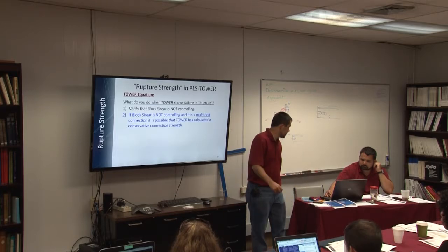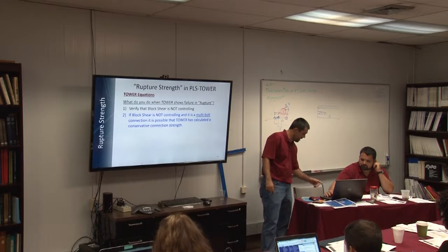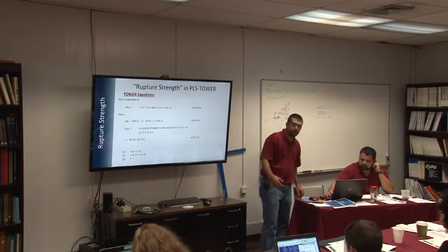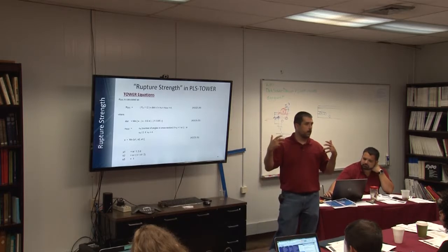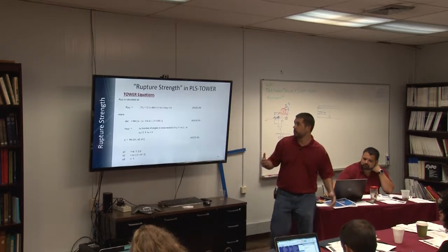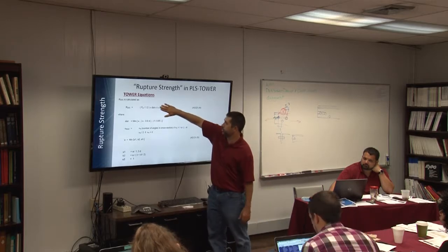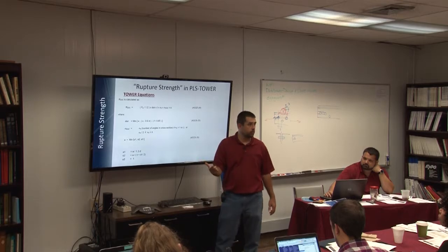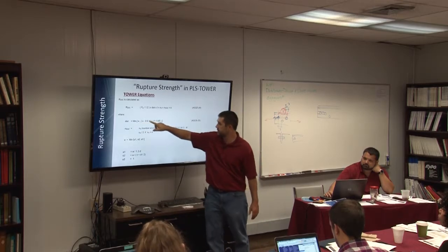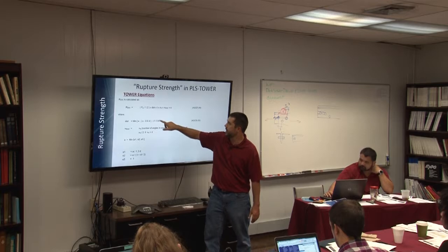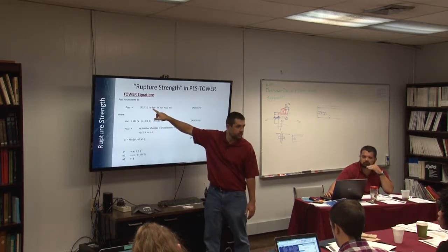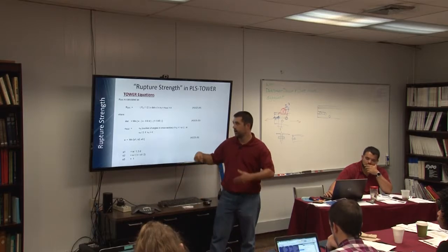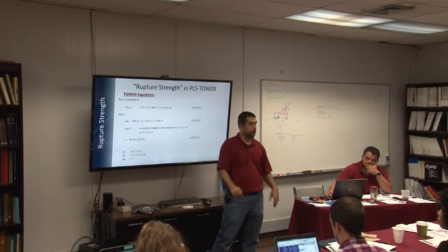And what I would recommend, if you wanted to calculate a different rupture strength, you could use this kind of approach from PLS: for every individual bolt, you calculate its distance, so the minimum of these 3 values, and plug it into this equation for each individual bolt and sum them up, right? And that would be a way to get another calculated rupture strength.